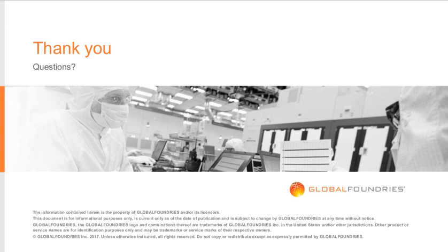How concerned are you with the heating effects in the SOI technology? Yes, the SOI definitely will isolate, so it's not good from a thermal conduction point of view. In this technology, we provide two solutions. One solution is the flip chip, and then we use the copper pillar to get the thermal out from the side. Another solution is that we provide a via-tie.